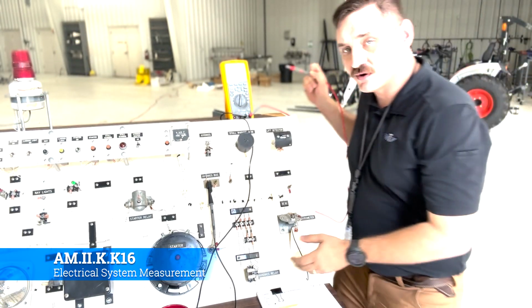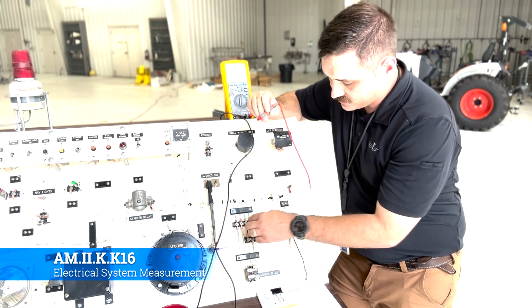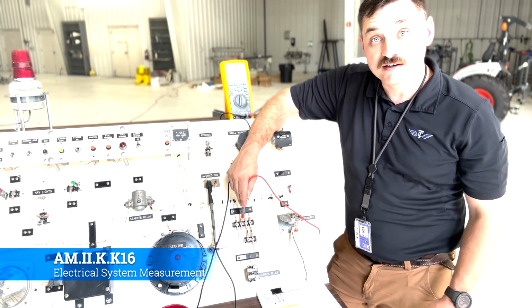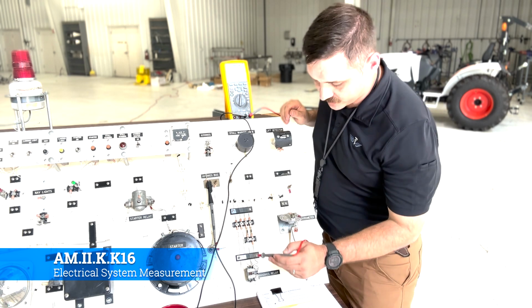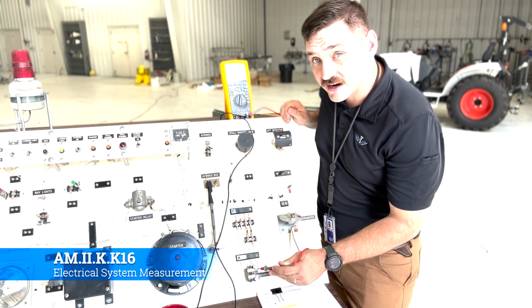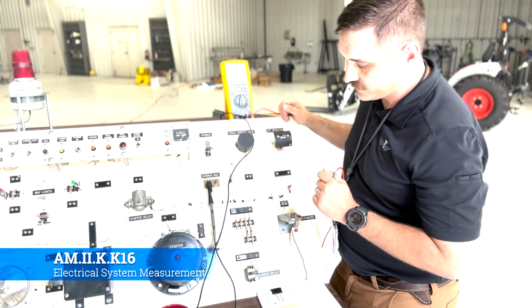So we're going to go down here to our avionics relay. We see that we have this bus bar here, and we see that R320 comes in right here. All right, and so we know that we have continuity from here to there. We know that the relay actually has continuity through it. So power has to be dropping off somewhere in there.